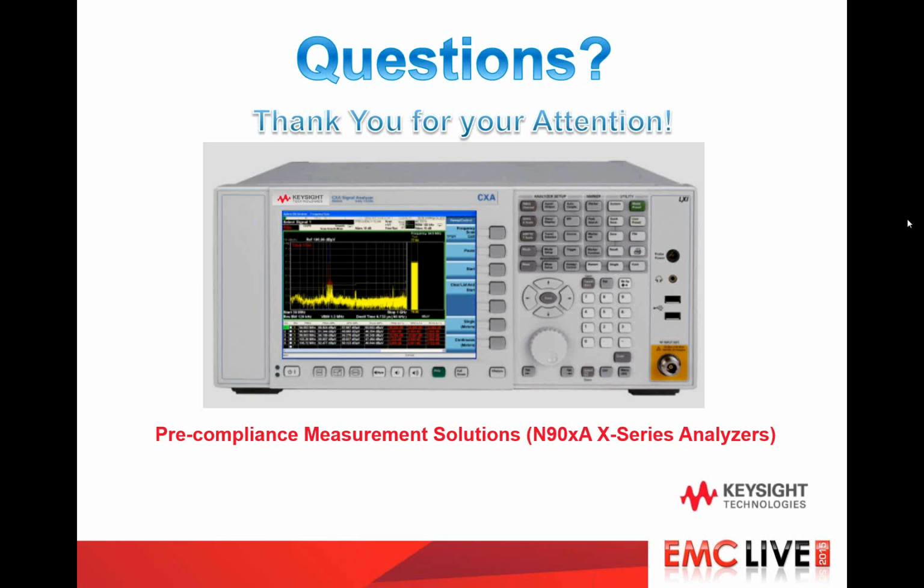Ken, here's a question for you. Is the quasi-peak detector hardware or software? The quasi-peak detector is actually hardware in a spectrum analyzer, so it's not software. It's not a calculated value. Again, it's a detector like a peak detector, but it also has a capacitor that's built into it, so that's what makes it unique.